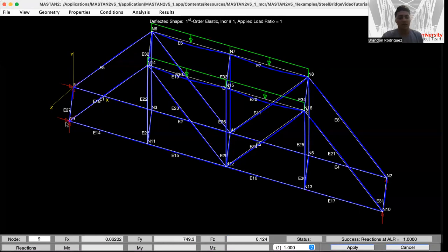And this is in the X, Y, and Z because we fixed it before in those directions with the fixity. So if you take the sum of all the FYs here at your nodes in the corners where we defined the fixities, the sum of them is the weight of your structure. So that's very important too when we're doing our optimization.